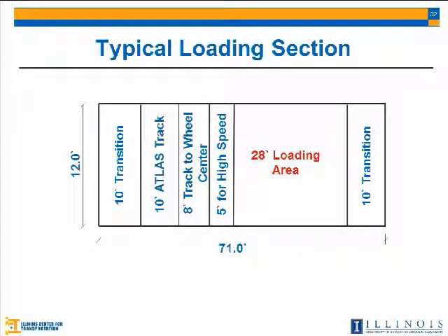But as we all know from asphalt materials, aggregate types can also play a big role in moisture damage, because there are some types of aggregates like silicate, or we have the limestone. Both of them behave differently when mixed with binder, and especially when moisture is introduced, because some of them like water much more than the others.